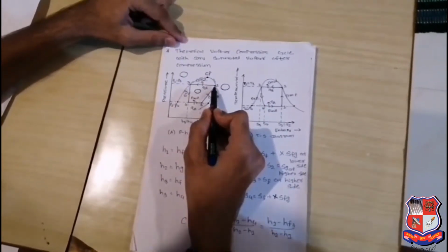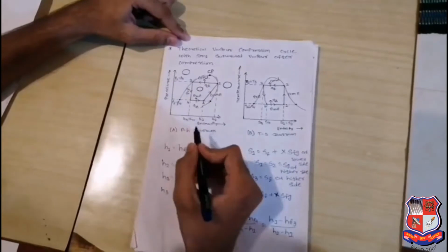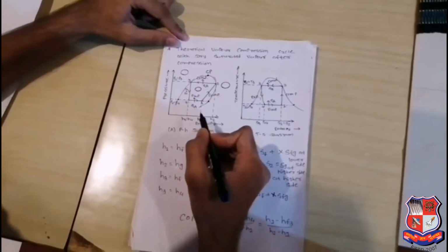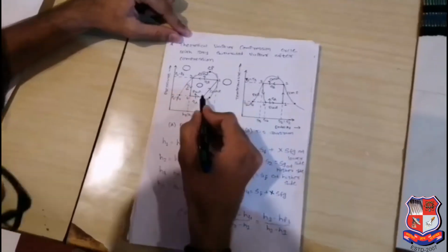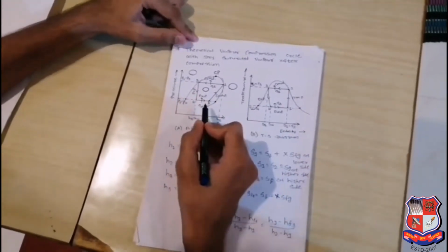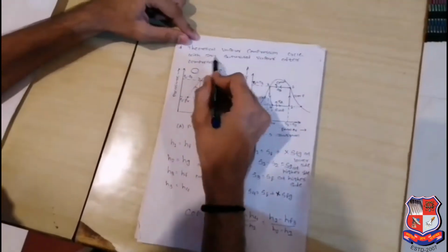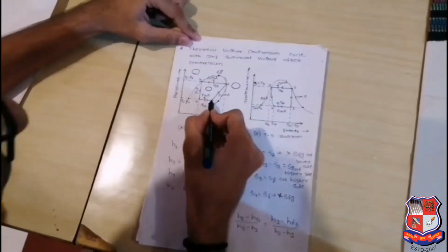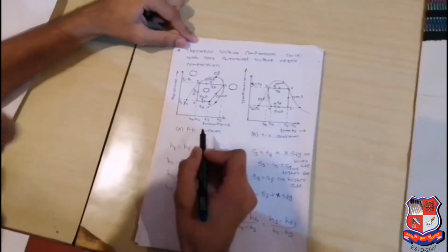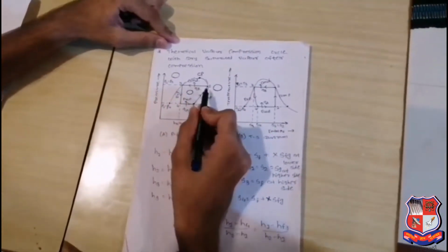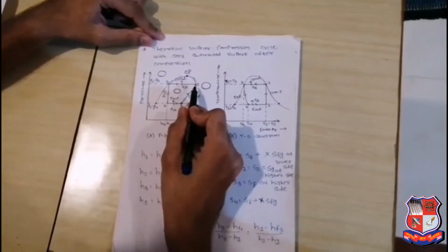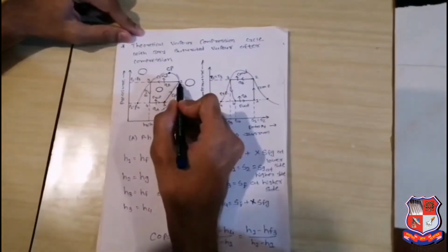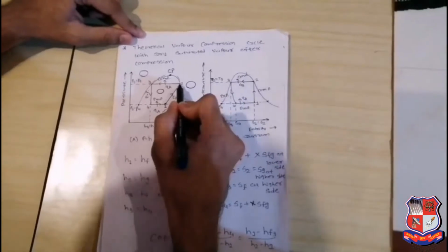Now in compression process, compression will take place, and during the compression pressure and temperature is increasing. So we can say that if we consider first point is wet region, so it will be possible to convert it into the dry saturated vapor after the compression. So first point will be considered in wet region. Then after the compression, pressure and enthalpy is increasing as well as temperature is also increasing. So at the time that wet refrigerant is converted into dry saturated vapor after the compression.